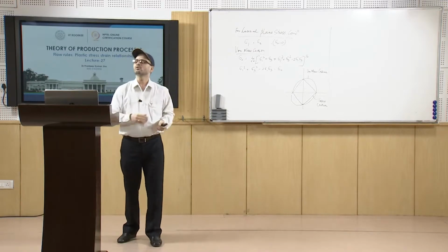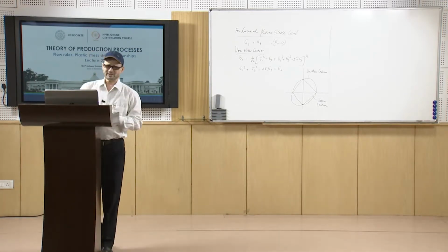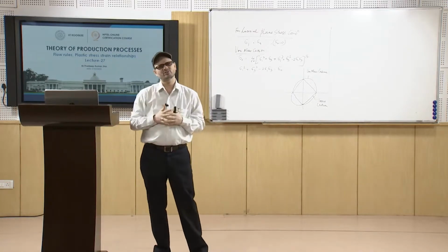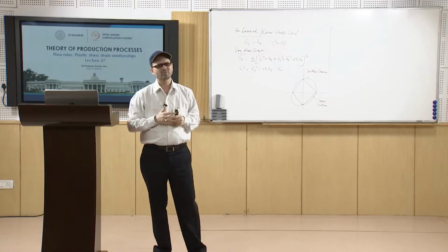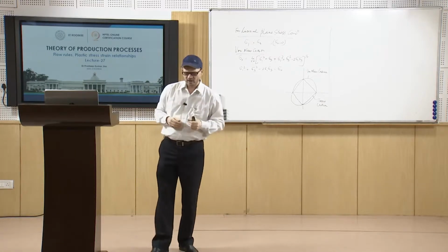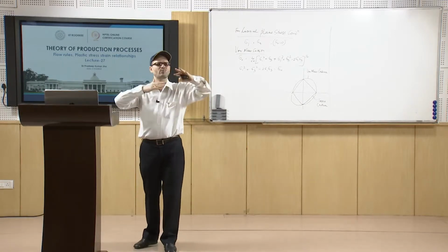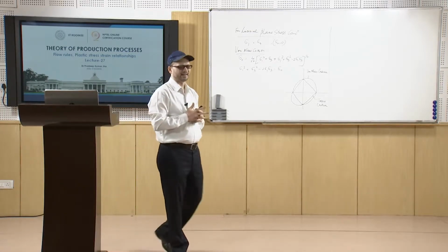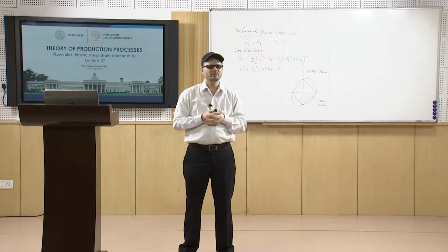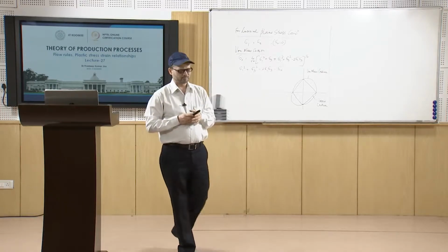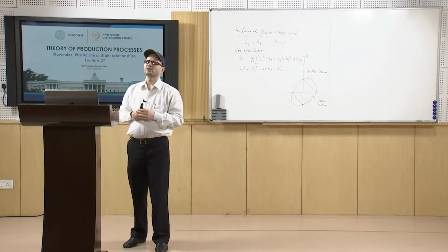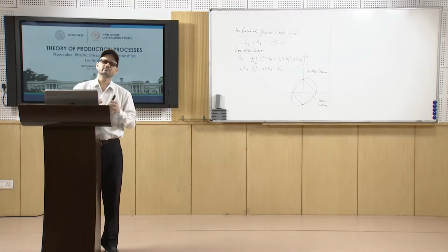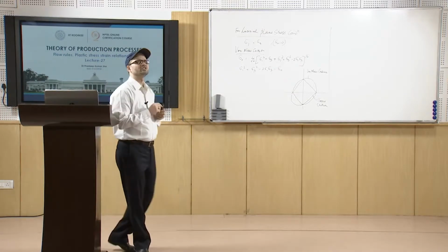So, how it is that we will see. Basically, that plane which makes the angle with the principal direction of stress of 54 degree 44 minute, whose cosine is 1 by root 3, is nothing but the 111 plane, that is the close packed plane, which we encounter in the case of plastic deformation. So, this is a close packed plane for shear occurring. That is the significance of the octahedral shear stresses.